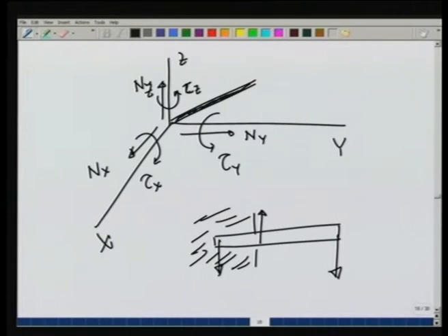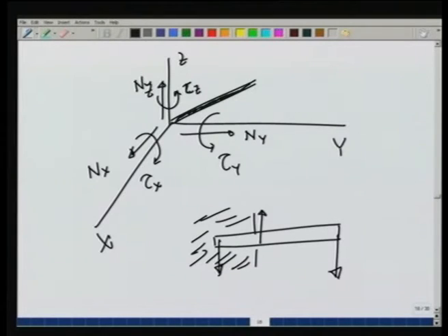And these provided a torque and a couple and a force. You generalize it to 3 dimensions and you will get the answer that a fixed support in 3 dimensions can provide torques and forces along and about all the 3 axes. Hopefully, by the analysis carried out so far, you would be able to now get an idea of what kind of force and what kind of torque can a new engineering element provide.